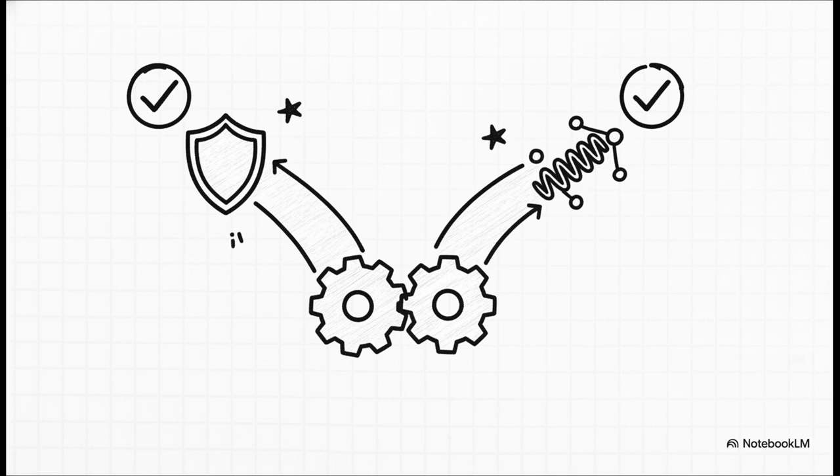Because the ratios match perfectly, you actually have a choice here. High impedance REF is safely on the table, which means you could use configuration D or H to protect that LV side. Honestly, this is often the traditional, ultra-stable choice that a lot of engineers specify by default when they've got matched hardware. However, low impedance REF, configurations B or F, is also fully compatible. It doesn't strictly require matched ratios, but it definitely accepts them, making it a perfectly valid and flexible choice too.